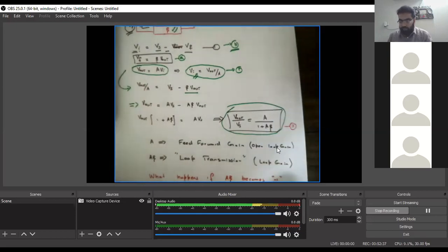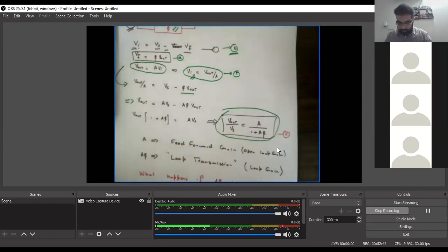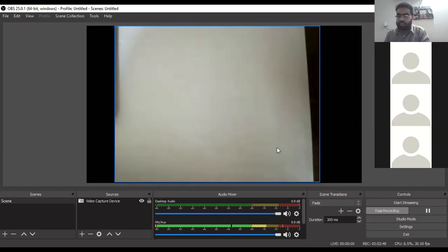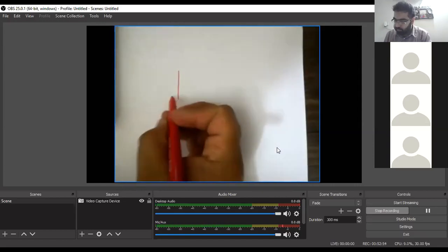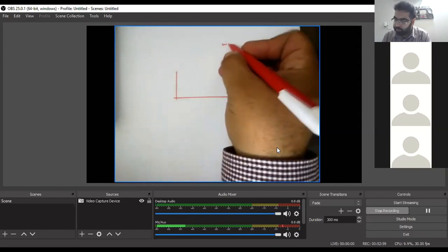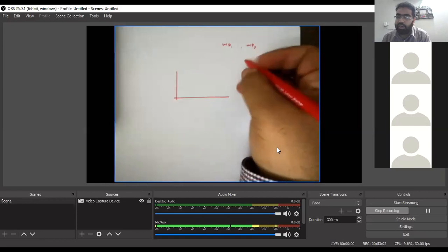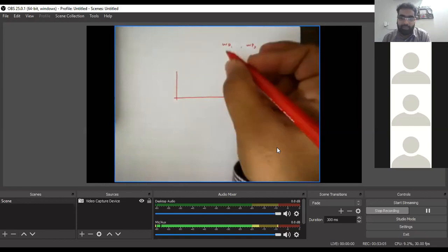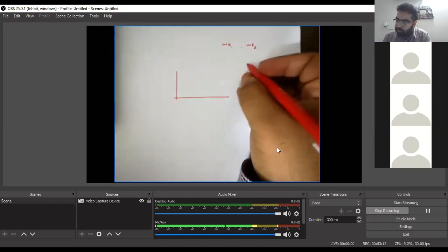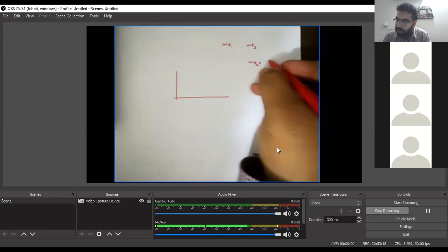they overlap. Okay, we can take one example of that one. So just draw the scenario, and if you think this is not the scenario you are asking, we can change it. Okay. So for example, let's take omega p1 and omega p2. So instead of the condition we were taking earlier, 100 times, they are like 10 times apart. Okay. So we'll see the effect: on magnitude it will not show. The main effect is going to come on the phase response, but we will draw both. So what you are saying is, if omega p2 is equal to 10 times omega p1.